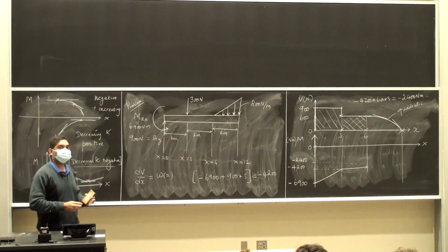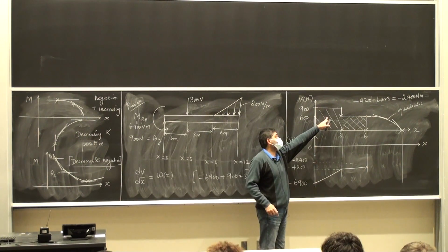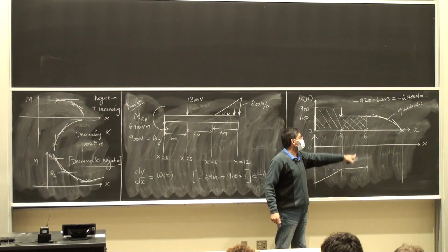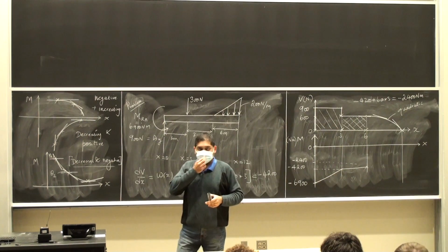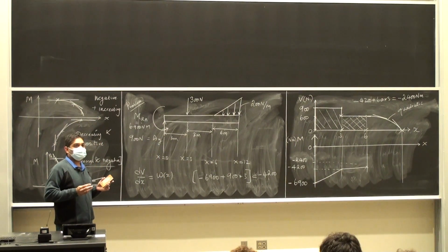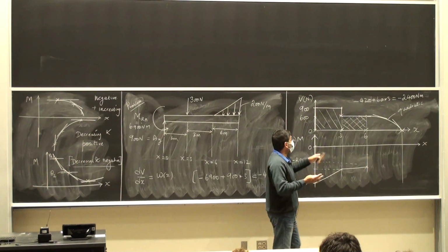It's not a horizontal line either, so I'm starting at a larger slope. Why is it a larger slope? Because the value of the shear force is larger here, is 900. The value of the shear force is 600 here. So the slope is smaller. But it's a positive slope because my shear force value is positive. And the bending moment itself is a linear line because the slope is constant.